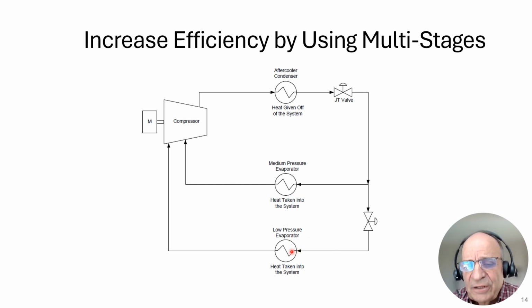The lower the pressure is at the inlet to the compressor, now you notice that I went to two different sections of the compressor, the lower the pressure is, the larger the compressor needs to be. And the reason is because the volume becomes much greater for a pound of refrigerant, and the compressor can get huge and uneconomical. So there'll come a point in time when we need to change the refrigerant that we're using. We'll talk about that.